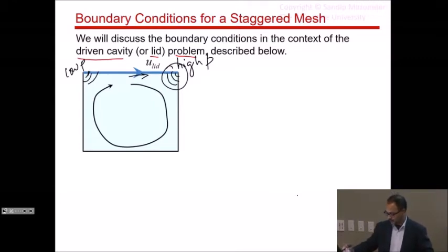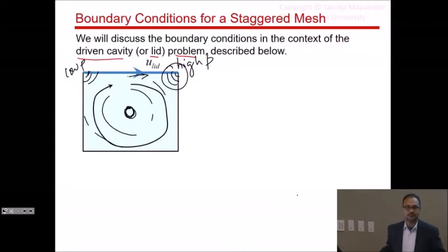And then as the fluid starts recirculating, this is the eye of the tornado or the eye of the hurricane. That's where you'll have small pressure. So you will have a blue region here for pressure if blue is low pressure and red is high pressure, and around that you will start developing these pressure contours. These are just some symptoms of the solution that I'm telling you, so you can check to see, am I getting something in the right ballpark? Any questions? This is the problem we are going to solve.